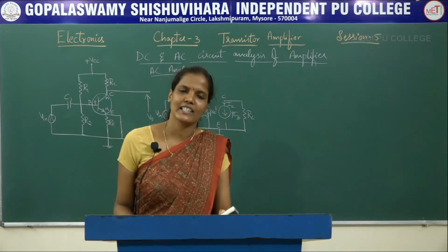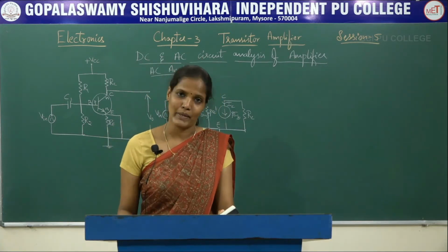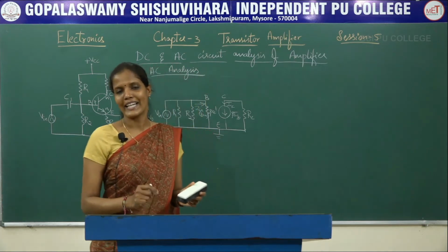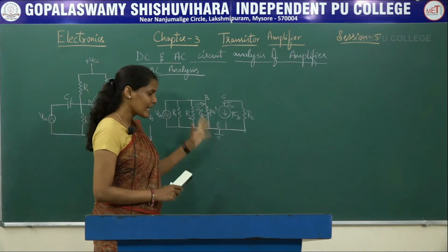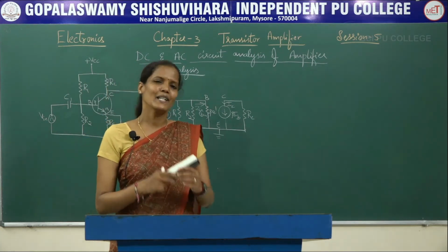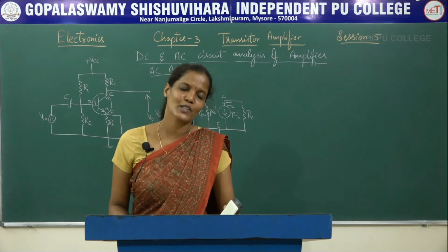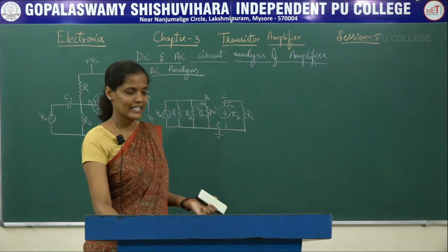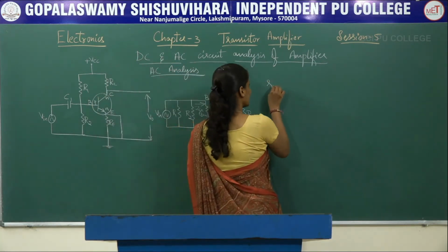This transistor is nothing but two diodes which are connected back to back. So whenever a small AC input signal is applied, the emitter diode will not rectify the signal, but instead it provides a small amount of resistance, which is called AC input resistance, denoted by RAC.